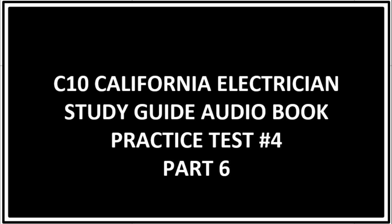Question 72. You are asked to remodel an office in a 7-story building and you are wiring a partition wall. What type of wiring would you use? EMT conduit. Use EMT conduit when wiring a partition wall in an office building.